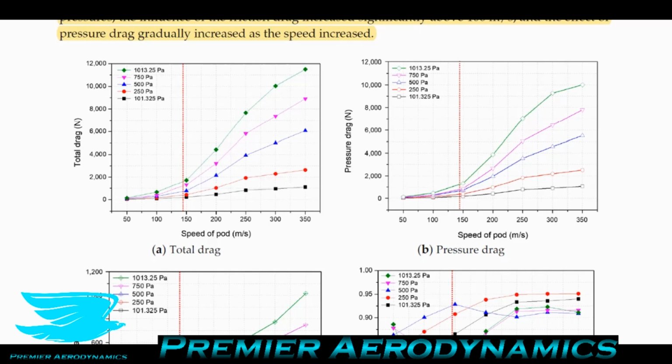But in this case, wave drag is when you get drag due to reaching the speed of sound. So you get this additional component of pressure drag. Effectively, it hides itself in this increase in pressure because of the shock wave that's being impinged on the object. So even though you can group it all together with pressure drag, you can actually divide the pressure drag into the non-sonic pressure drag part and then the wave drag part. So you can divide this even further.